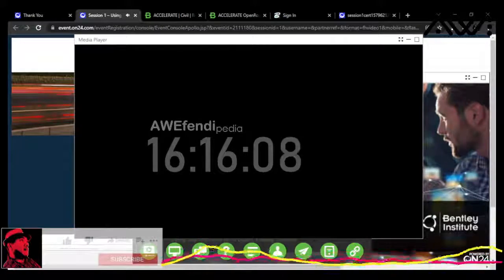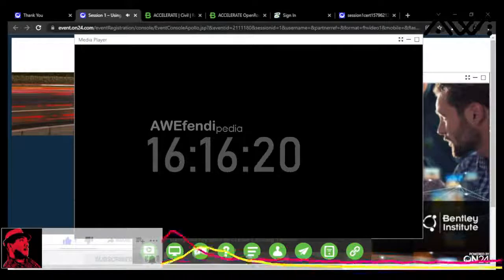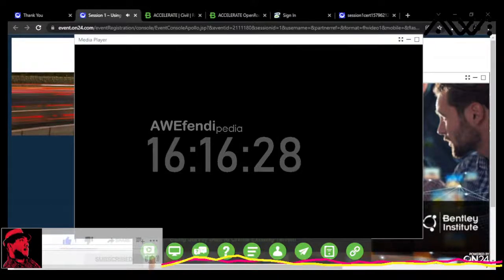And so that's what I did. I created a new string code, and this point was collected after this point, so it worked for me. If I don't want to worry so much about the order of the points in the field book, then I might want to think about using pointless features, and we'll do that here in a second. So our driveways are fixed up here now. I'm happy with that.